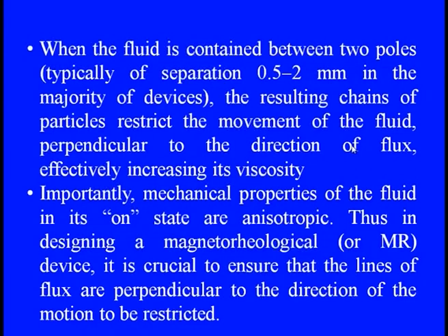And moreover, you see here the mechanical property of the fluid when it is in the on state is anisotropic. Thus, in designing these MR magnetorheological devices, it is crucial to ensure that the lines of the flux are perpendicular to the direction of motion which is to be restricted. Say we just want to put resistance in one direction, the applied magnetic flux should be perpendicular to that direction only.